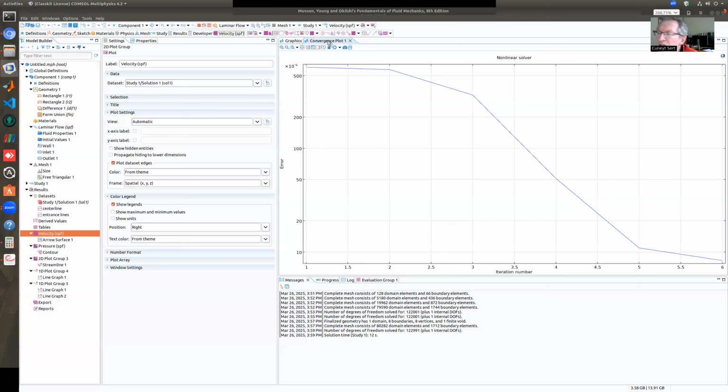So in CFD, depending on your selections, depending on your mesh, depending on the Reynolds number, other things, the geometry, the shape, it's not always possible to get a solution. Sometimes the solution just doesn't converge to some meaningful final result. It just blows up, or it just oscillates and oscillates, and the errors do not drop.